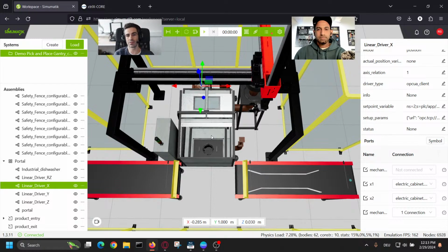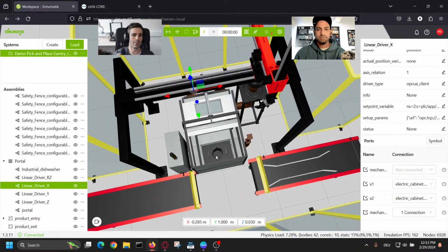And different manufacturers have different approaches. They kind of idealize this servo or this axis. So when you call a move absolute or move relative function, they will generate an ideal path. Right. And basically the set point and the actual position in the controller will be the same. Right. With pretty much no delay. And in those cases, we cannot do much because it's a limitation in the PLC controller.